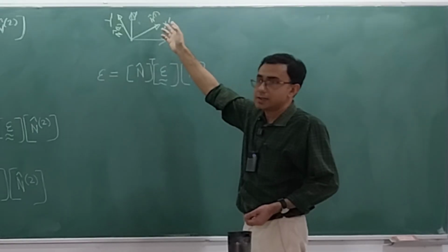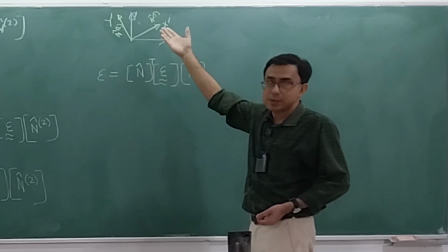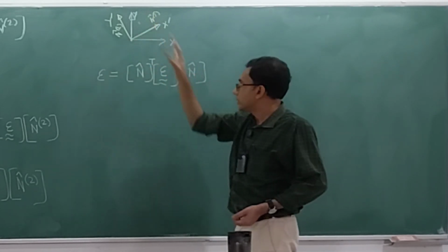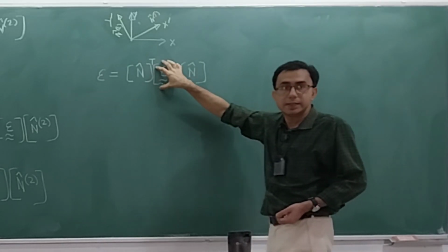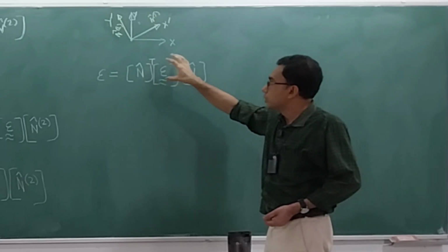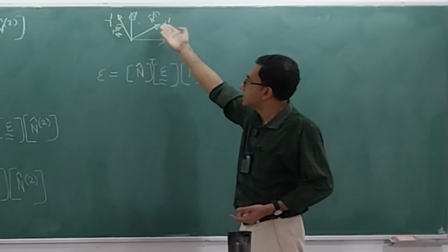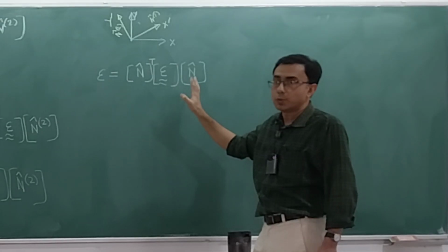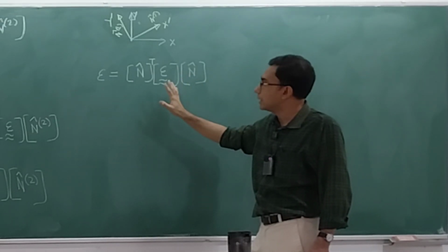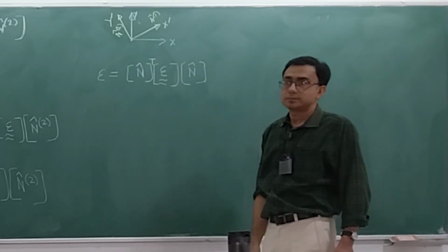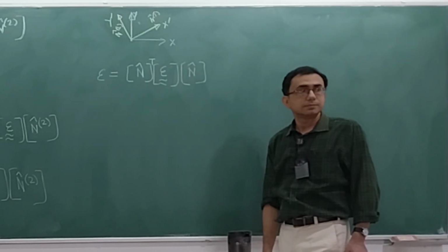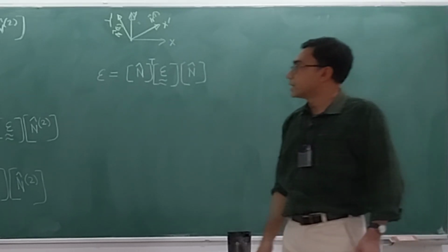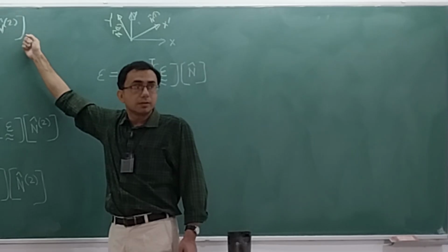So if you have this x dash, then along that you have a unit vector. If someone asks you that, given the state of strain at a point with respect to the coordinate axes x and y, you have this information, all the 6 independent elements, using that you just need to be asked what along a certain direction, maybe n1, maybe n2, maybe n3, whatever is given to you, just substitute it here. What you will get is the engineering normal strain along that direction. That's it. Considering theta equal to 90, the general formula is this, and this is only for specific cases.